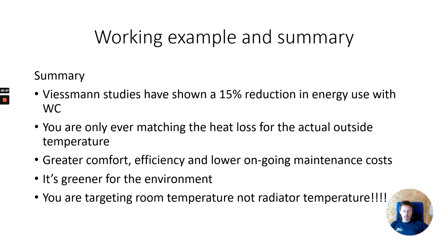If we've got Jim down the road and he's had a back boiler, so his radiators take the skin off your hand when you touch them, and they were coming out at like 85 degrees, I could go and fit a weather compensated system for him, and although the room is at 21 degrees, he might be ringing me a lot until he gains the understanding that it's the actual room temperature we're targeting, because he's going to touch the radiators, they're going to be lukewarm, and he's going to say that boiler's rubbish, I don't get any heat from it. And it's not that. We're targeting room temperature, not radiator temperature.